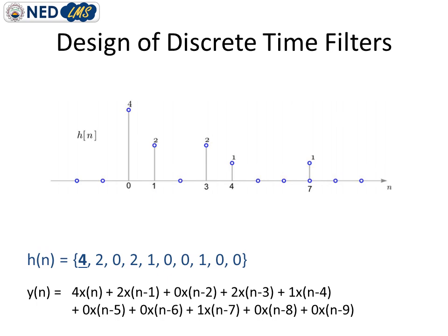So to design an IIR filter, we need some special technique, and the design method actually uses a mathematical transformation known as the Z transform. As we already learned the Fourier transform, the Z transform is similar to the Fourier transform. It is a mathematical tool whose origin is basically the Laplace transform.